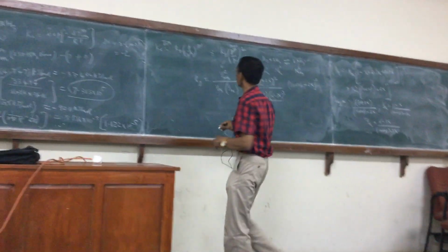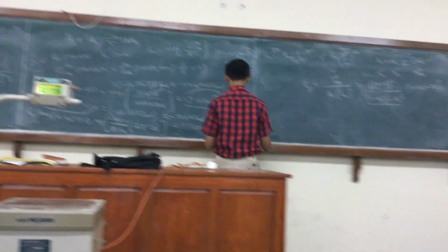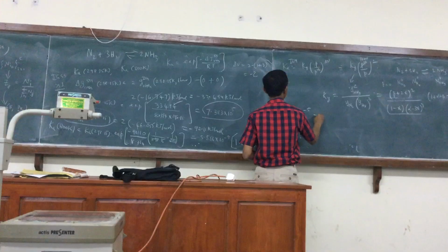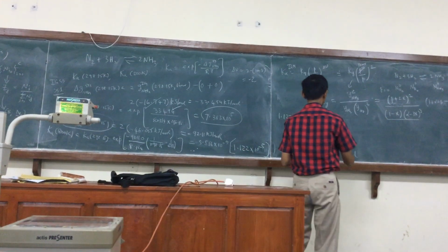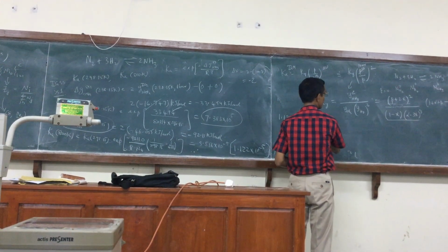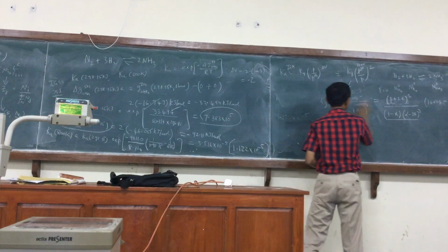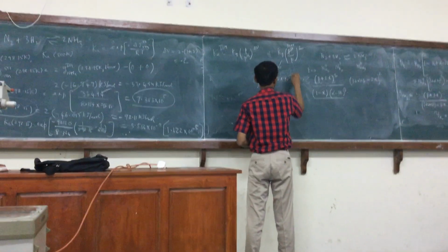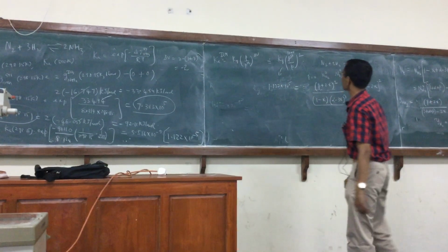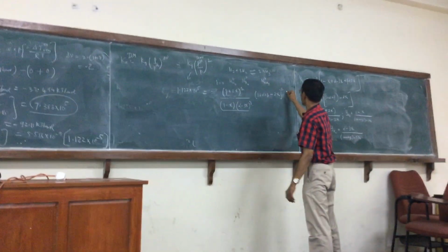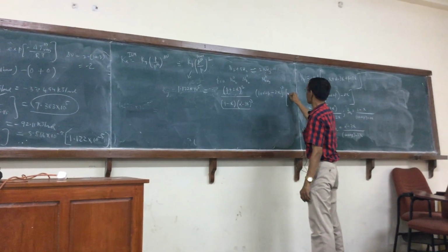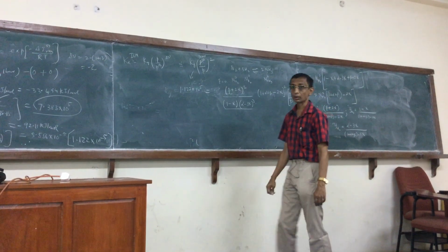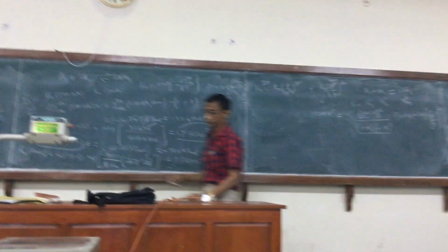So now what we have is that whatever we have calculated, 1.122 times 10 power minus 5 at 800, is to be Ky, all of this. So I can write it here. We have to have the correct Ky times P over P standard squared.